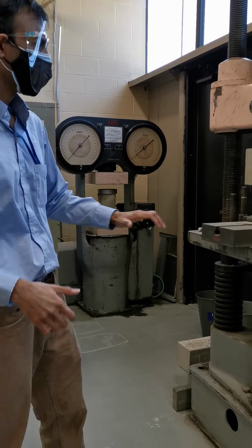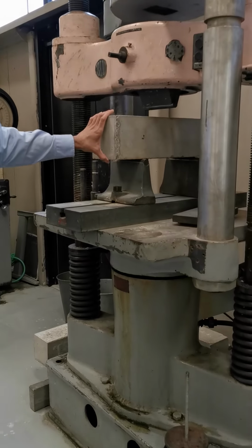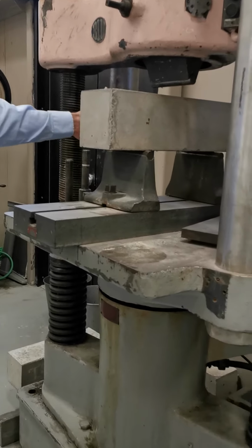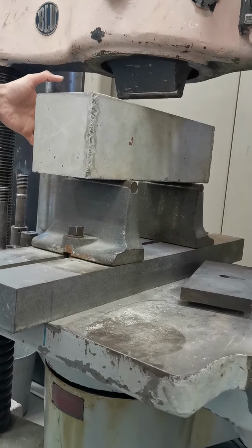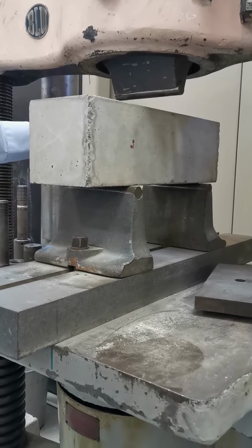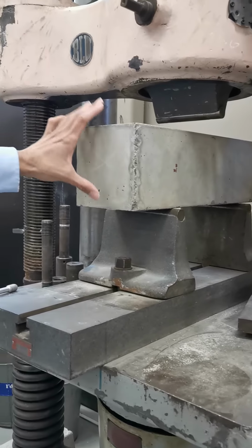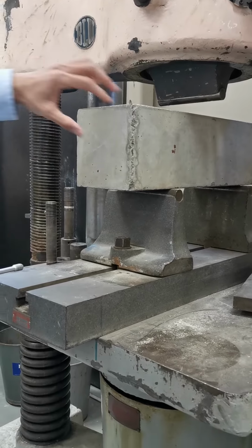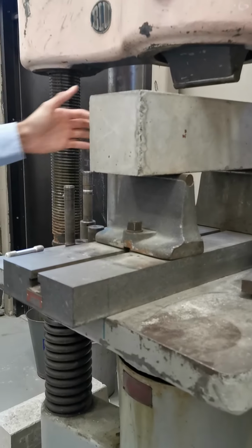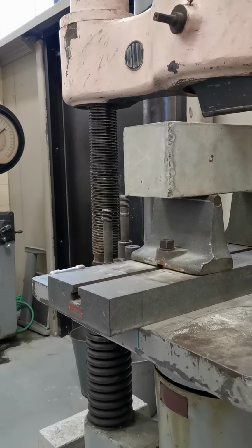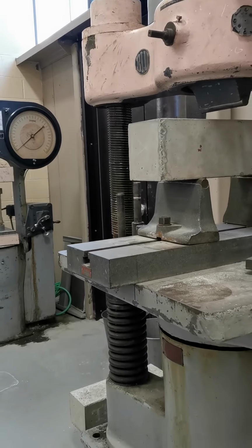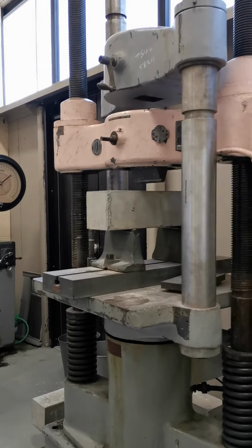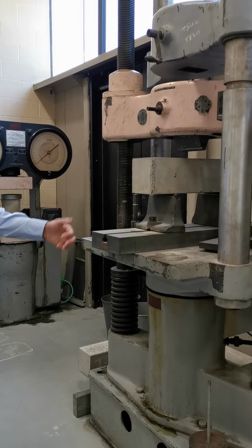And for the modulus of rupture, we are using a 6-inch by 6-inch beam with a 12-inch span. Therefore, there is a considerable deep beam effect. The students also try to simulate this and observe the arch of compression while doing the simulation. So they are able to get a deeper insight into interpreting the results of the experiment.